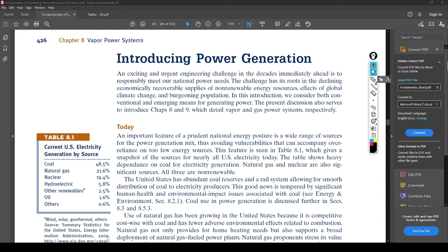And then after it goes out of the turbine, we need to get that steam, whatever mixture it is, either superheated or, usually, saturated or superheated still, back to the first state, right? Because it's not a cycle unless it gets back to the first state. So we have to find a way to get it back to the first state. And how we do that is we run it through the condenser.